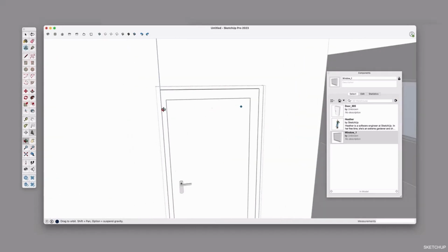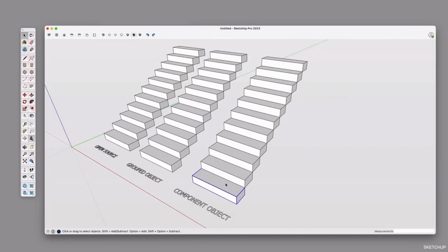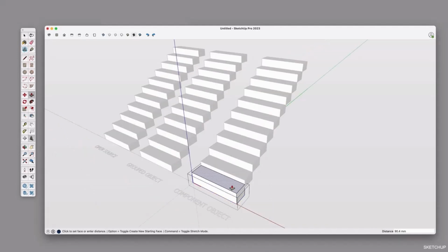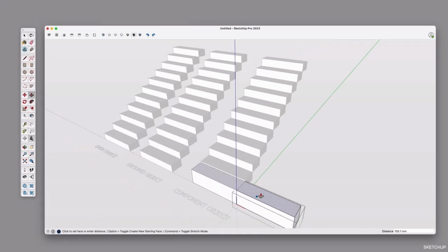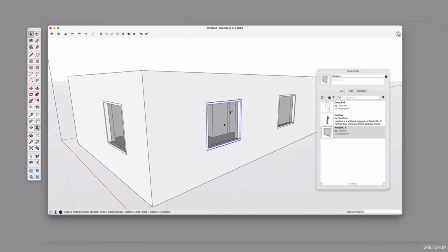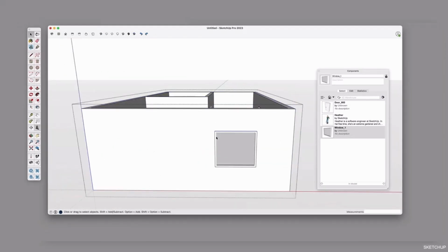In the case that for some reason you need to isolate a component from its clones, you can select that particular component and choose Make Unique. So changes made to this specific component will only affect itself. But when we copy this unique individual component again, you create another clone and it retains its association with the original unique component it was created for. Hope that makes sense to you.